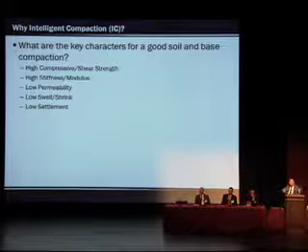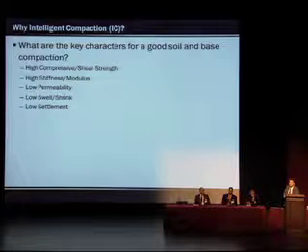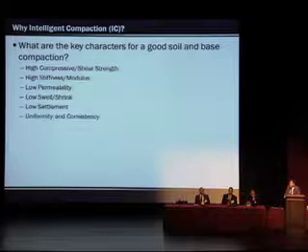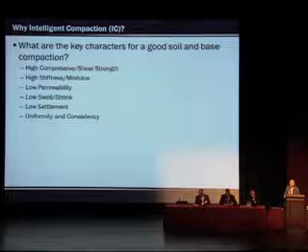Why do we have a pothole here, not 100 feet away? Why don't we have a pothole everywhere? We have some localized areas. Homogeneity, or uniformity and consistency. We are missing that. To me, that's the most important characteristic for good compaction.